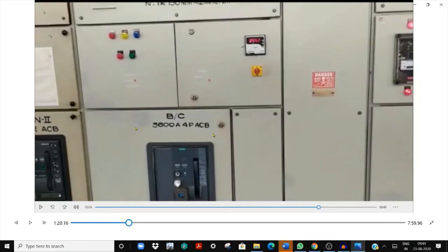So they independently feed their units during full load condition. Only at off load or one quarter of the load are we shutting down one of the transformers. The bus coupler will be closed when one source is active and the respective load is connected. When both sources are active, the bus coupler will be kept open.